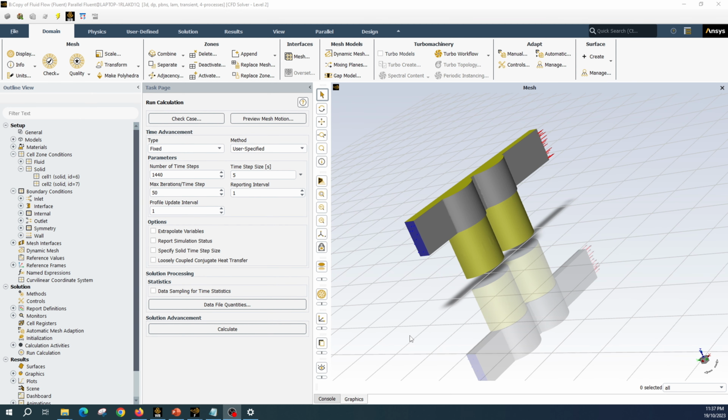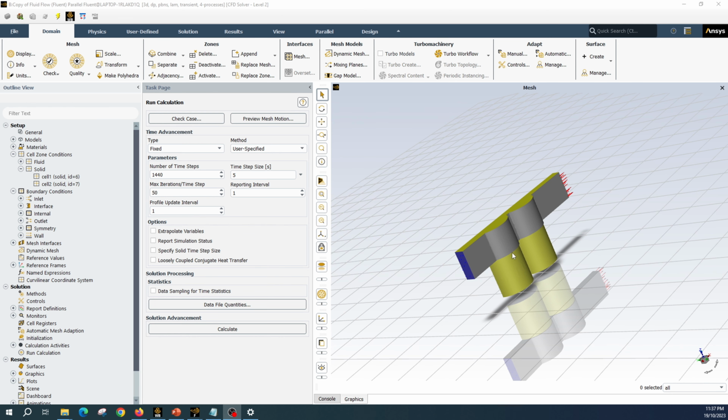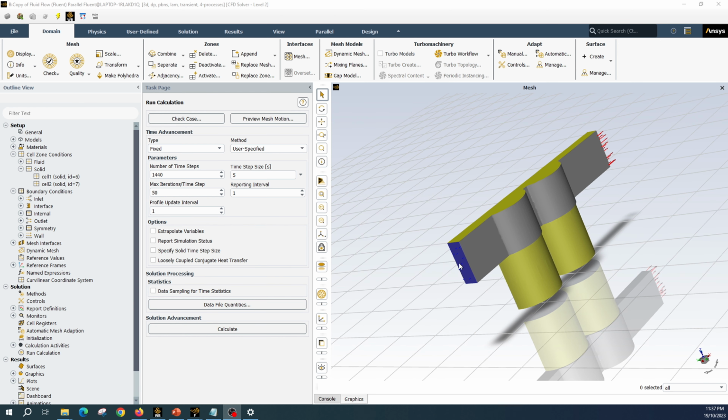Here is a Fluent case. As I mentioned earlier, we will simulate only 1/4 of the geometry. So here is the inlet, these are two battery cells, and here is the outlet. Let's continue with our different definitions. Everything we will define over here in the named expressions. A few things we can define directly, but we will do everything over here.